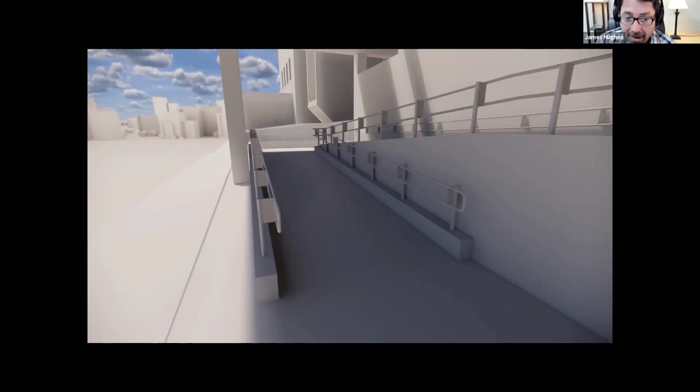Now we've left it monolithic because this is existing conditions. I don't need to make it to where we can stretch posts around. They are exactly where they go. But then I just save that RFA file and I load it into the project as a component and then just place it. And it is exactly the height that it needs to be. And then I erase the model in place component and put in the RFA family that's there. And it's a really solid result.